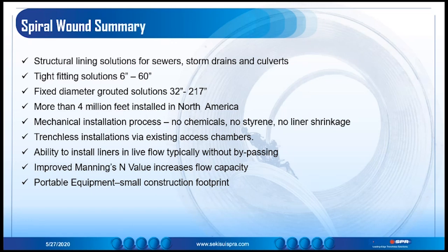All right, thank you, Chris. And we have a question about grouting here. Maybe you can handle this one as well. For fixed diameter liners, what testing is done to verify that the annular space was grouted completely? Sure, Ryan. Typically, a common tap test with a rubber mallet is done. The amount of grout that's pumped will correlate to calculations as to how many cubic yards of grout would be required. So during that tap test, if it's determined that perhaps not enough grout was in a section or a lift near a grout port, the installer will simply remove the port and inject more grout to be sure that the annular space has been completely filled.